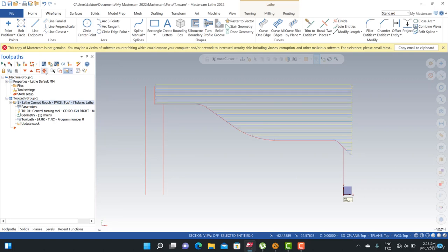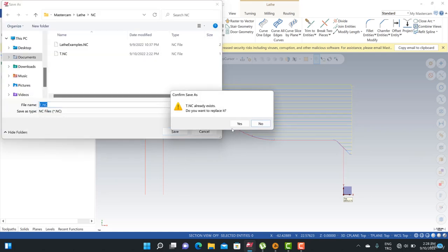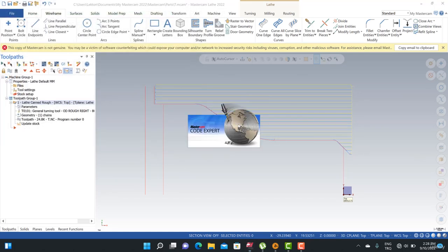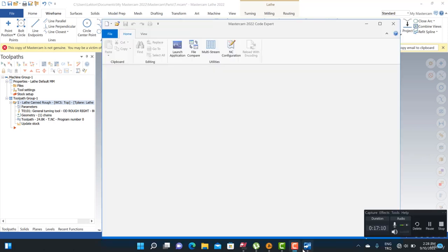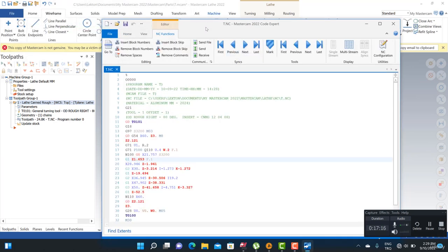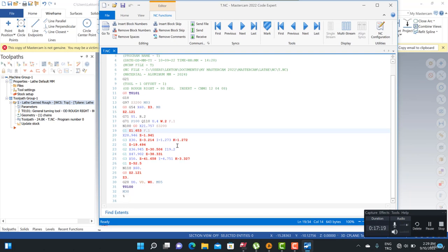Okay, I'm going to hit the G1 button to get our G code. There's an 'already exists' warning, and then we're going to see our G71 options. Okay, this is the G71 options. It's active right now. I just need to change my parameters if I don't like my depth of cut, my retract, my stock to leave on the x-axis, and my stock to leave on the z-axis.